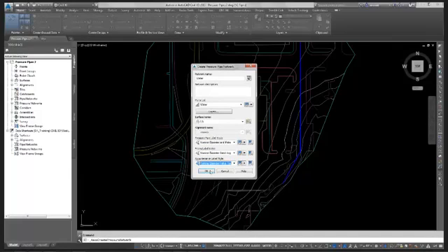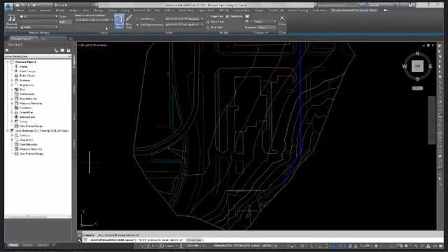Obviously, use whatever label style will match your company's, but I'm going to get in and show you how to modify these labels to make it look a little bit more appealing. Instead of ductile iron pipe, it actually says DIP and things like that. So I'm going to say OK. And it instantly took me to the plan view ribbon, and I have all my pipes.